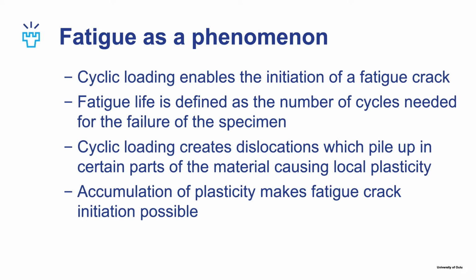A little bit about fatigue as a phenomenon. Cyclic loading is what enables the initiation of a fatigue crack, and fatigue life is defined as the number of cycles needed for the failure of the specimen. This fatigue life can be divided into two parts. The first is the initiation and propagation of a microcrack, and the other is the growth of the microcrack to a macrocrack, and the growth of that macrocrack to the failure of the specimen.